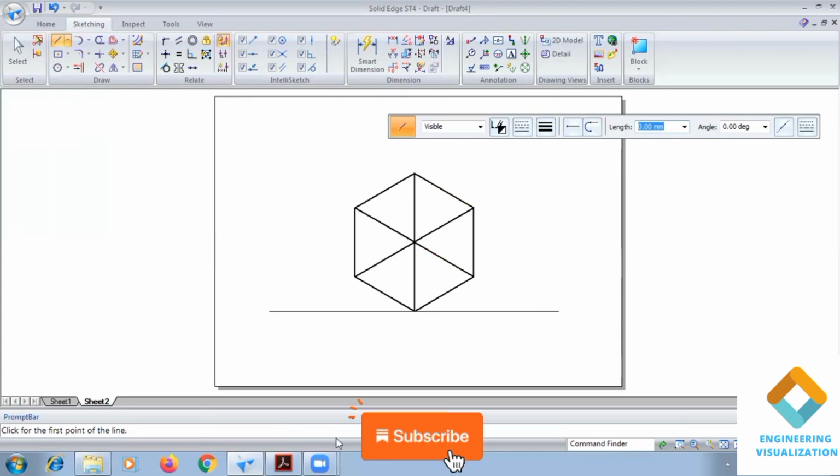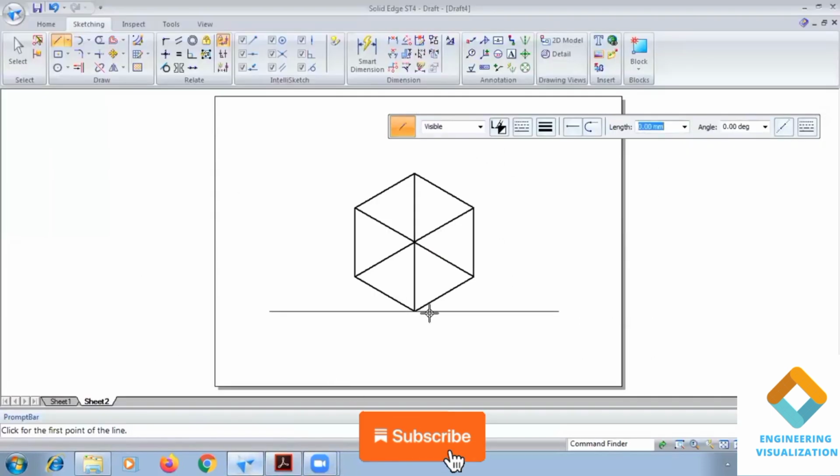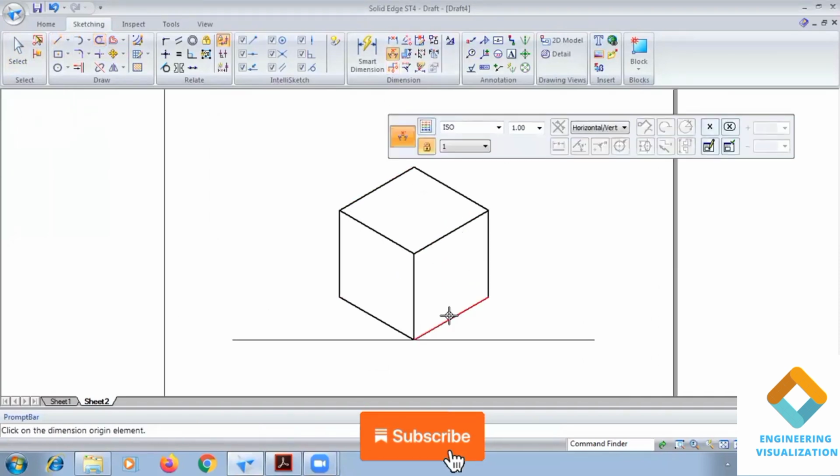Above it centrally we need to place the sphere here. That is also having dimension 50. But guys, you know that the sphere will be constructed with the actual scale, but the cube we need to convert into isometric here. So that is the important thing. You can keep it like this. Then you can show the angle.